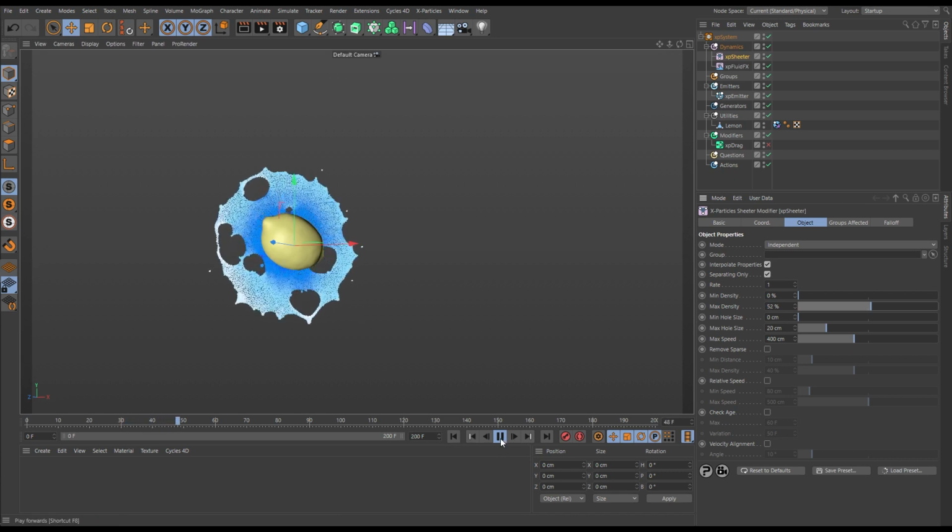All right. So we have a setting called remove sparse, and this is for when the sheeter creates particles and those sheeted particles are created kind of almost too much in isolation of the rest of the simulation. They'd be considered a sparse particle, and they might not look very good within the context of your simulation, and they may not mesh very well. So you kind of want rid of them. We don't want sparsely spawning particles. For most scenes, you won't need to use remove sparse, so only include this if you are getting these sparsely spawning sheet particles.